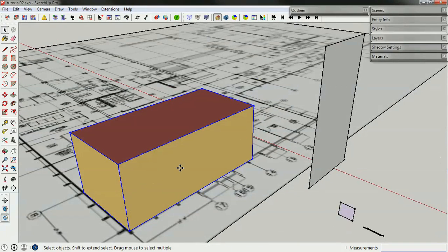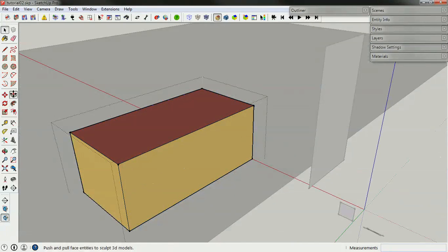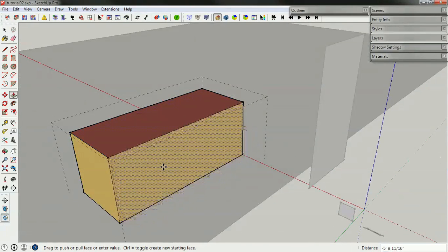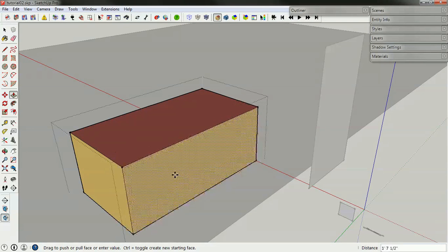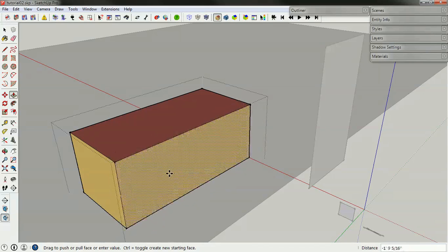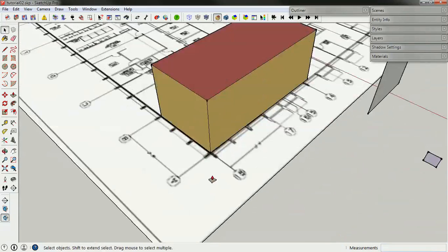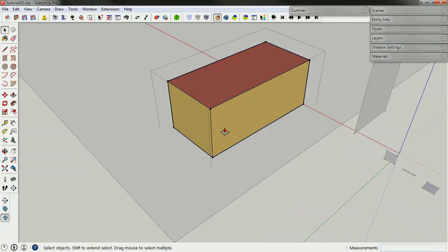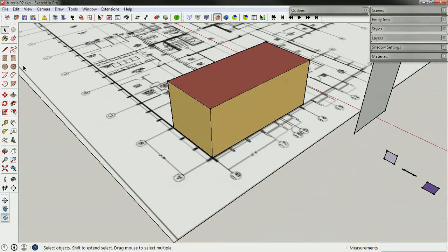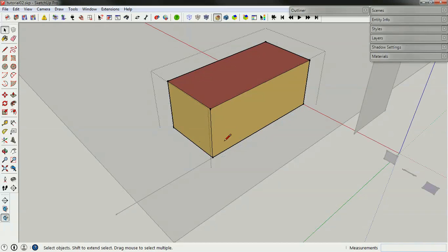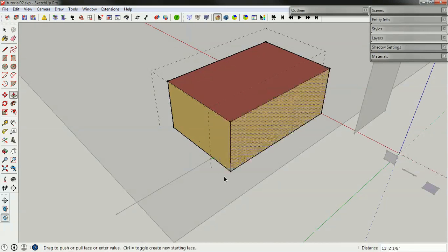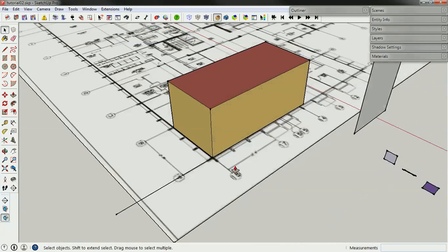and then I'm going to push-pull this face. So I'm going to double-click, press on push-pull, and I'm going to push this until it's in line. Now I just realized that, oh, I was a good guess too. When I double-clicked, the background went to gray, so it was difficult to see what was going on. And so another way of doing this would be to make a line at that edge where I wanted that boundary to be, and then I can snap to that line.